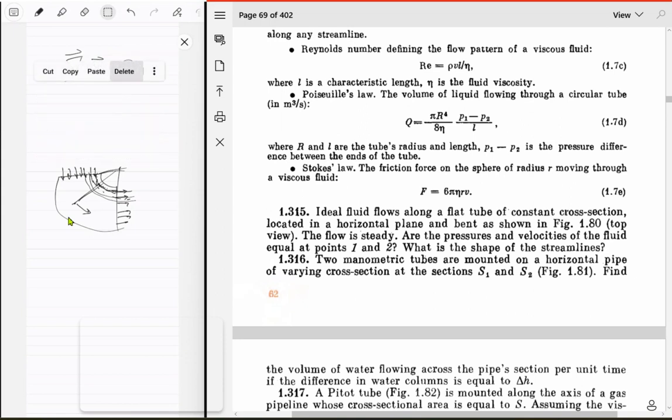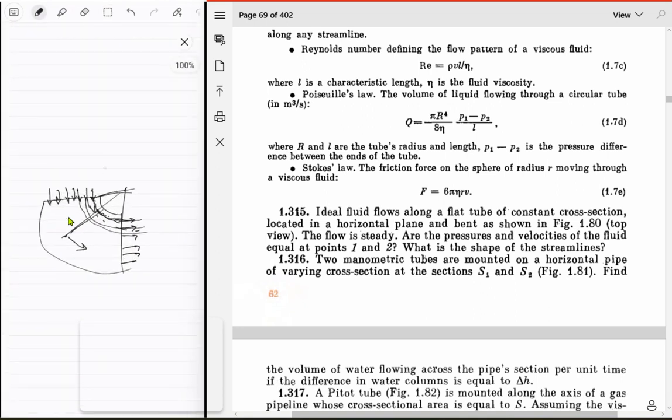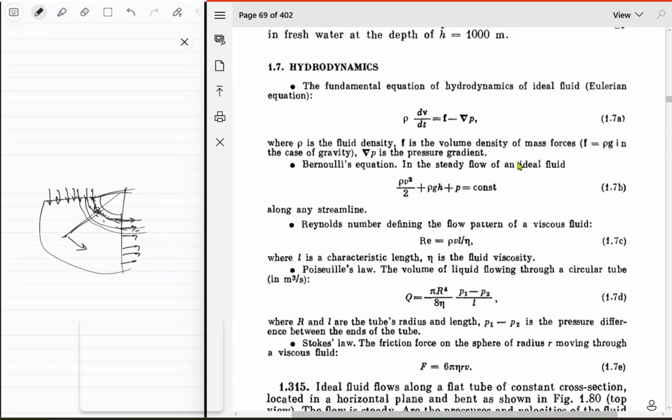So now what that means is you can use this fluid flow that you have. Every block is moving with u tangentially, and just plug that fluid flow into this to get some stuff about pressure. So dv upon dt for any block as it moves, what's the dv upon dt? Just the acceleration, which is of course just v square upon r. So just have the density, and then you get the acceleration, which is v square upon r in the negative r hat direction.